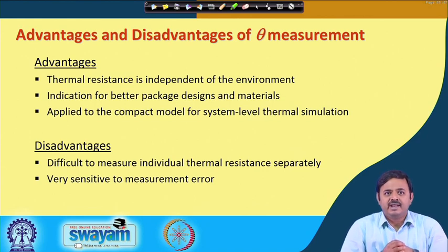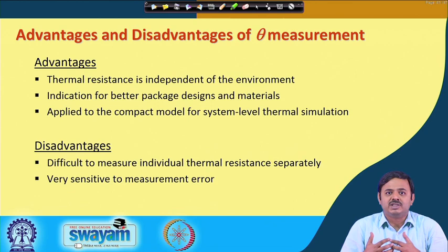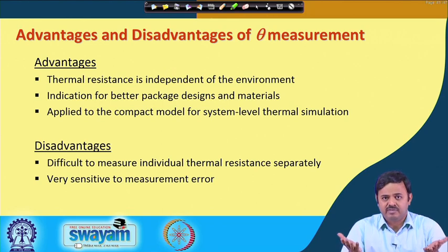Another advantage is an indication for better package designs and materials, because if you can measure it, you can say, oh, this theta is very low, which means the thermal solution is very good. And it is a very useful tool to make quick estimations for system level thermal simulations. We will see that later.